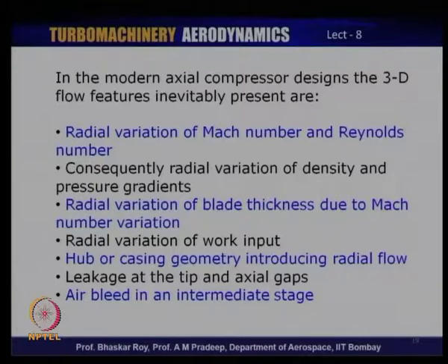Then consequently, the blade thickness also would vary from root to the tip due to the Mach number, and as I was just mentioning, that low Mach number near the root would warrant low speed aerofoil choices. At the tip, high Mach number would warrant choices of thin aerofoils, which are meant for high Mach number. If it is supersonic, you would need to choose supersonic aerofoils. We will discuss those aerofoil issues later on in this lecture series.